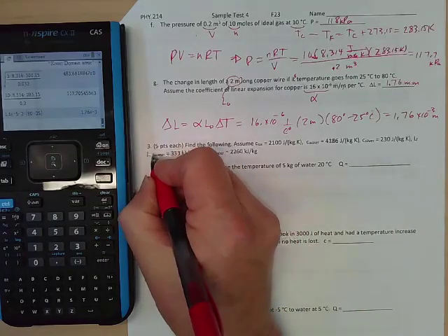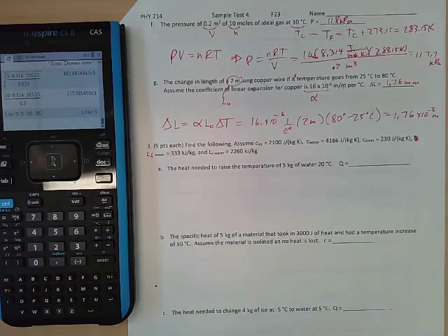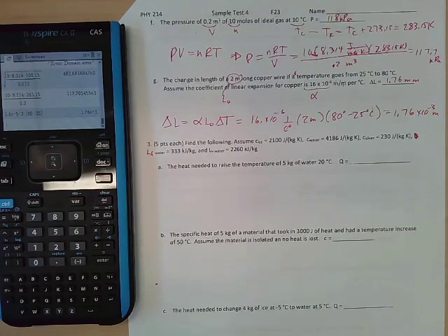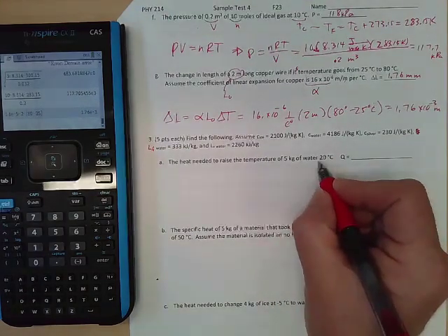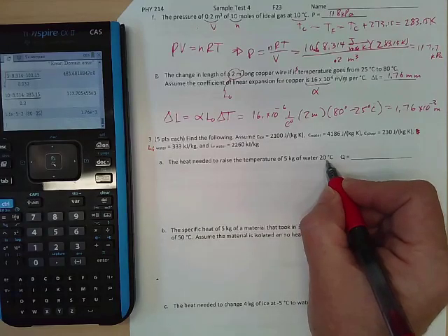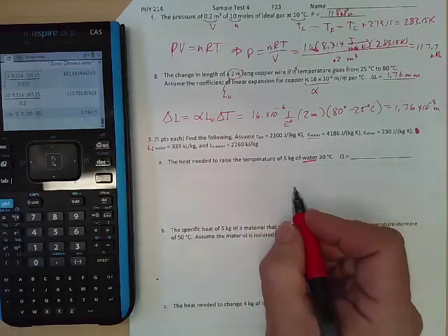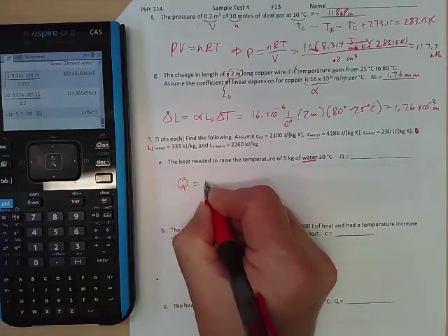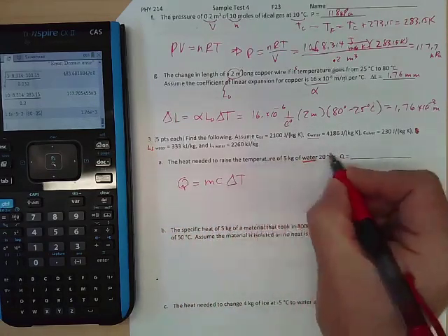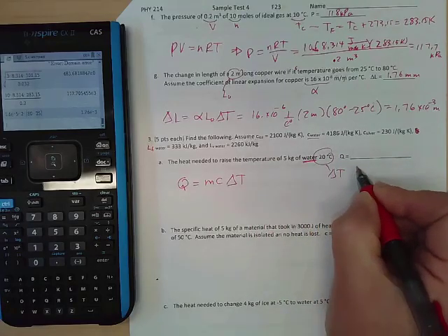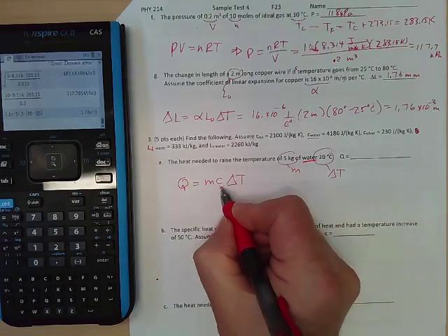So this is latent heat of fusion of water. Put it all over on that side. Alright. We're going to have these numbers given. We want to find the heat needed to raise the temperature of 5 kilograms of water 20 degrees. So it says water, we're going to assume it's liquid water, and it's just all liquid water. So we're going to say Q then is mass times specific heat times the change in temperature. This raised 20 degrees, so that's going to be delta T is given. Of course, this is the mass. And specific heat of water is given here.